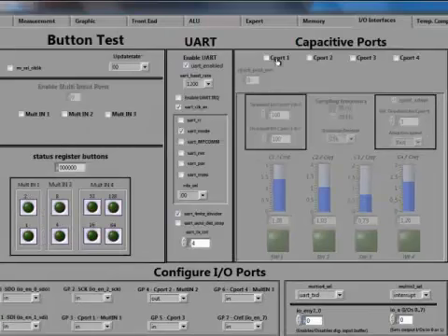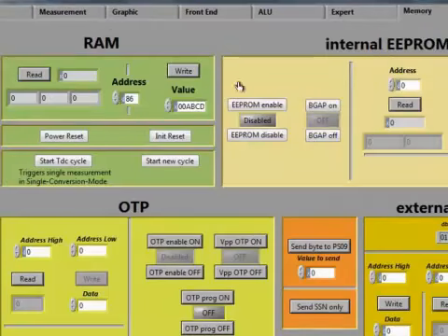Then enter the bytes in RAM address 86 onwards, 3 bytes at each address. This has to be done on the memory sheet. At RAM address 86, the data entered is ABCD. CD will be the first byte to be sent. AB will be the second byte to be sent.